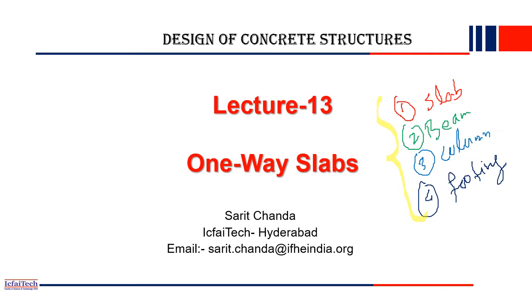Earlier we already discussed the beam part, how to design the beam. In this lecture and the next few lectures we'll discuss slab design, and later on column design and footing and foundation design. This completes a structure. Any structure, building or bridge, is composed of these four elements: slab, beam, column, and footing. Loads are transferred from slab to beam, beams are connected to columns, and columns ultimately rest on a footing.